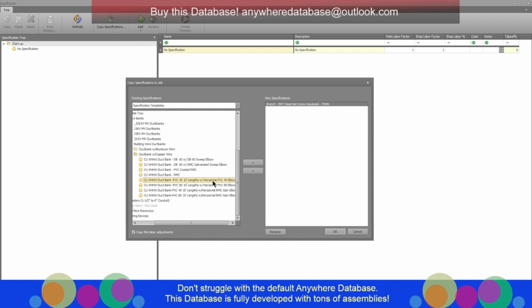To me, there's a huge difference between a horizontal elbow and what its material type is versus what's coming out of the ground. When it comes out of the ground, it could be many, many things. So maybe we'll take a look at that and I'll further explain. But for this purpose, I just want to clarify that you're not defining the vertical stub ups out of the ground at this level. It's only in-ground conduit and horizontal turning elbows within that run.